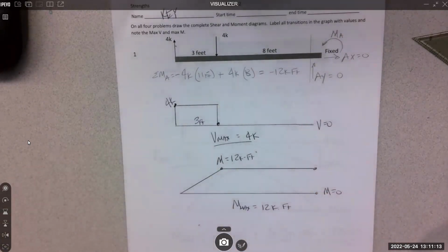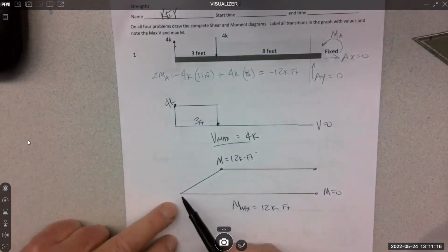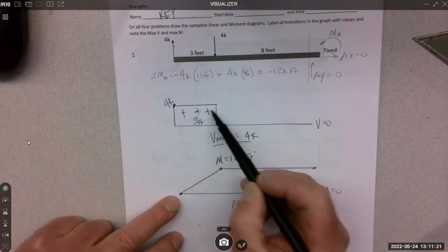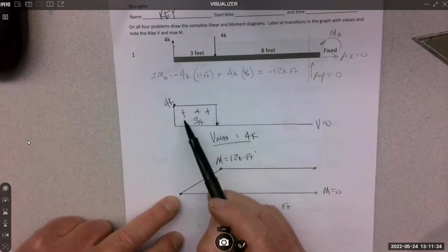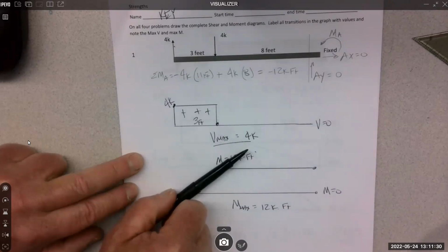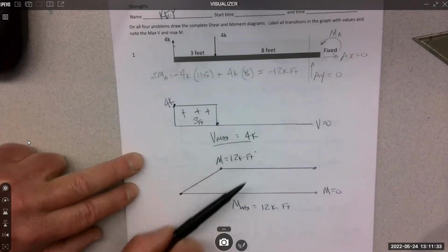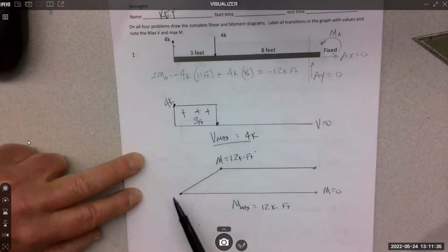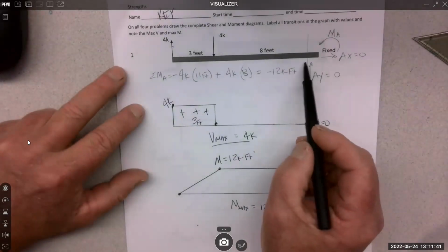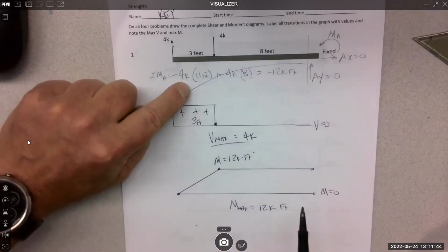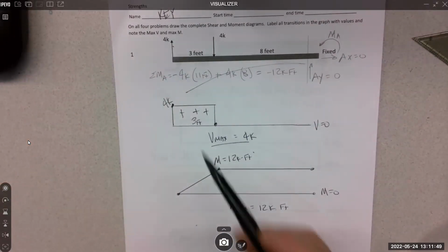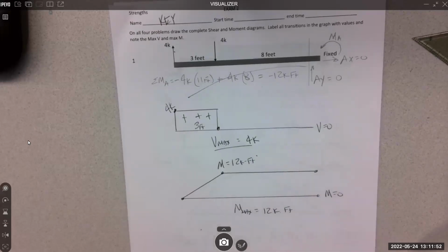And then the maximum moment down here, starting out here, it's 0. It increases because we see this plus. Remember that plus is the slope. It doesn't necessarily mean that the moment's positive, right? It just means the slope is positive. So it could be down here, but it starts from here and then slopes up. So it's definitely up. And we know that this kind of a deflection is a positive moment. Okay, so up, up, up, and then nothing changes.